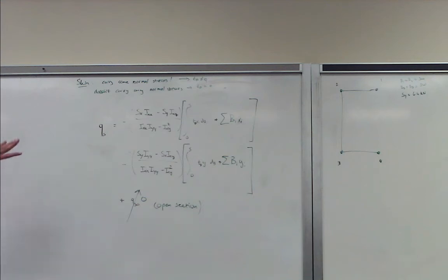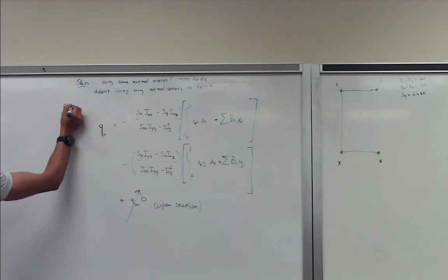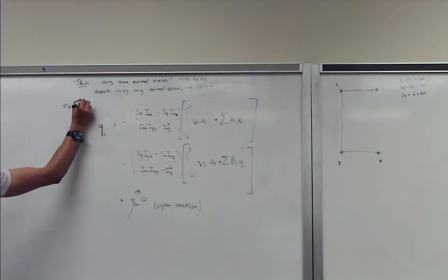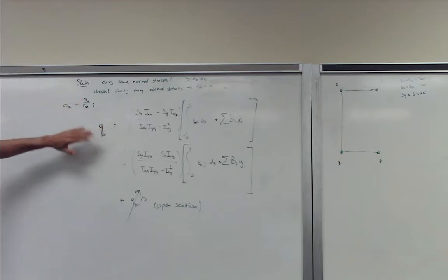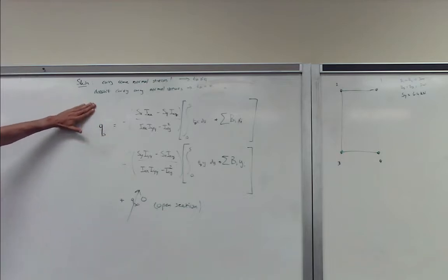And this makes more sense, because this equation, how we derived it, basically came from our direct stress equation. That was our generic version of this equation, where we substituted the force, moment, and shear force relationships into it, and then we got our shear flow equation.